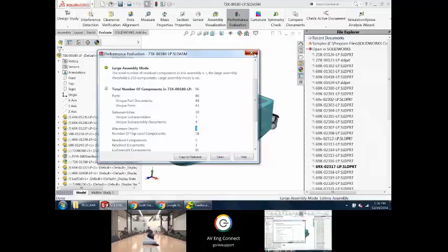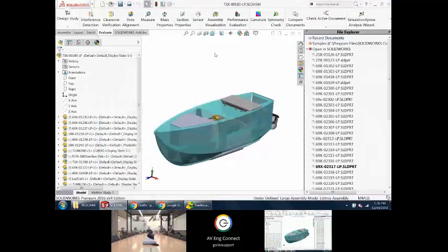Okay, but that's a little bit about the performance of just opening up an assembly and working with it. So there's things that have to be loaded. You have to load the files themselves as far as the RAM and the feature manager tree hierarchy. The files come with parametric data. The more difficult the surfaces are, the longer it's going to take to draw the pictures, but also if you have a part that is underdefined, all your sketches don't have all the dimensions in them, it takes longer for that to load up.